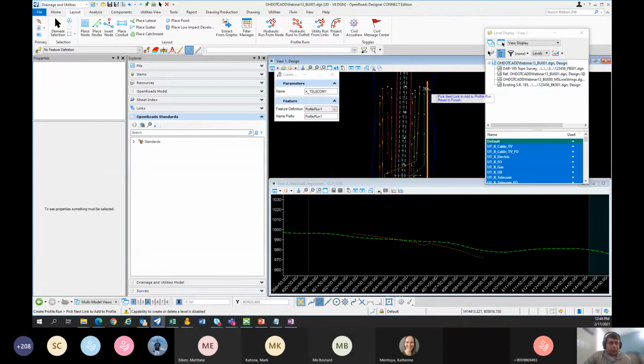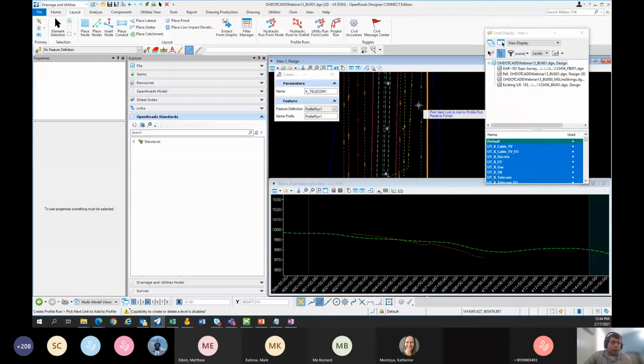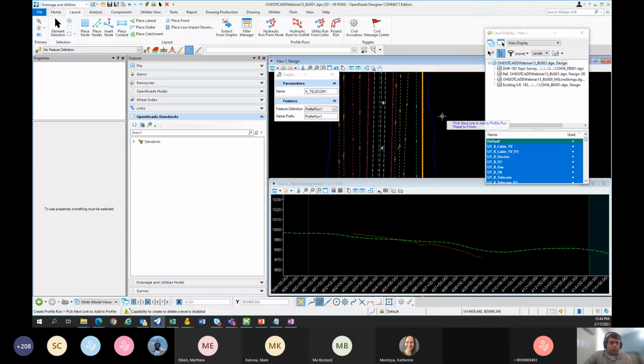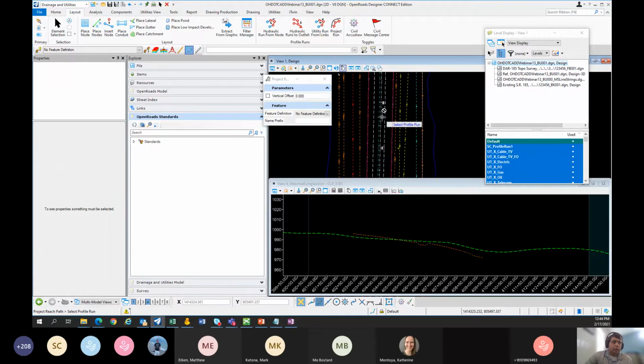Now these runs, when you want to select more than one run, that means it's still connected. You can't go jump over to somewhere else. So that's the only one I have to select. I'm going to reset to finish, and it will create a profile run graphic right there. So now with that profile run graphic, I can project that run onto my center line, right?